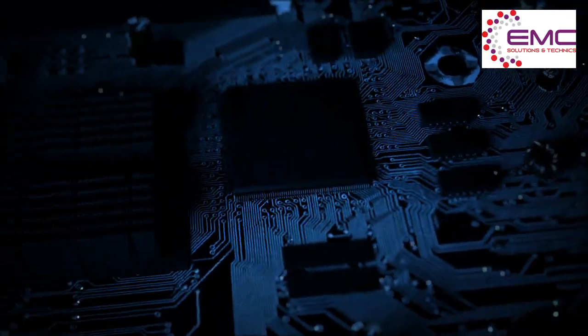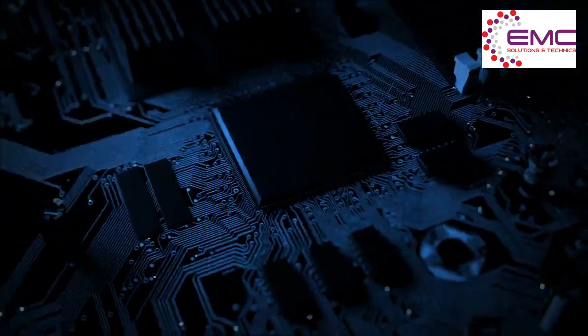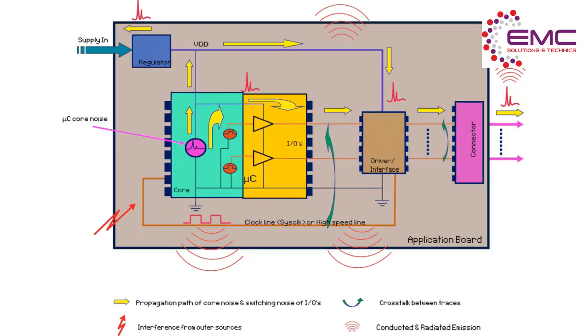and EMC. Many factors contribute to vulnerable EMI designs. These include mixing noisy circuits, such as power lines, and switching circuits like motor control with digital and sensitive analog circuits. Locating clock drivers too close to board edges or near sensitive circuits.